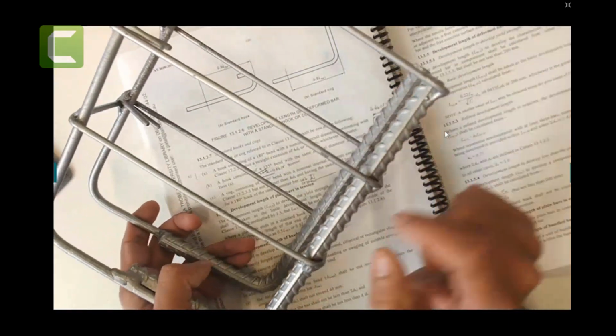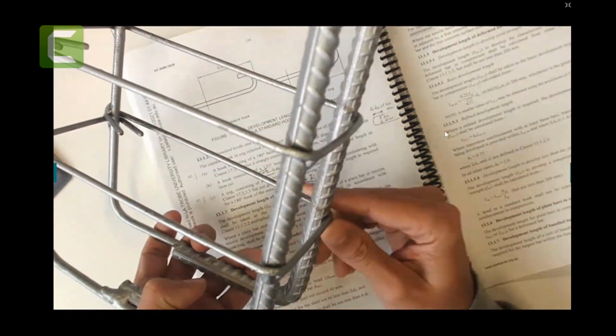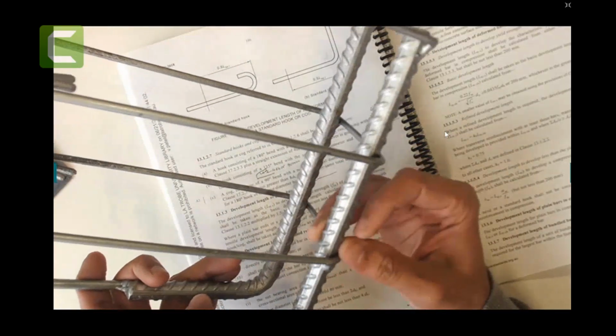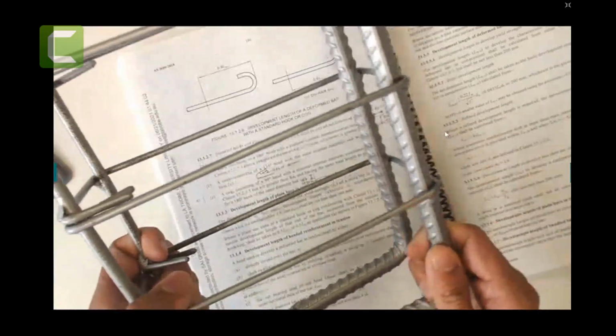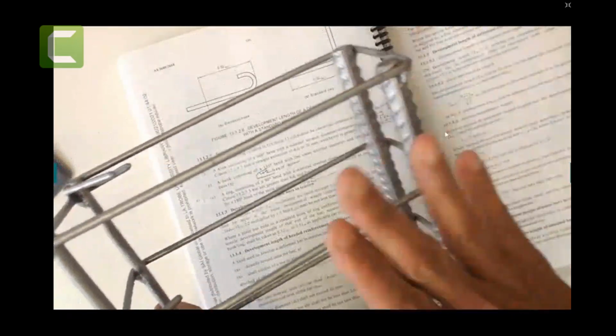Now here, if I have these stirrups, you look at those stirrups, right? Those stirrups are going to hold these wires in position. So it is our friend that will even give you more gripping. As you can see, these are going to hold more, and it will provide the confinement in the concrete. So this concrete will be confined in here. So this is our friend.